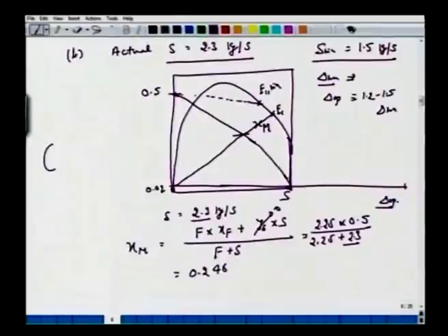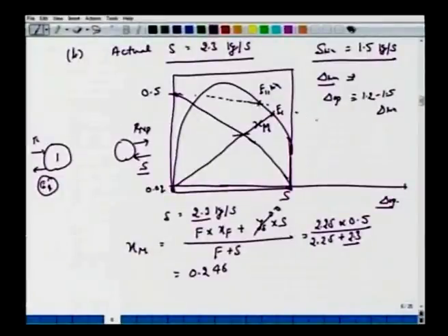So it is a multi-stage: feed getting in here, raffinate getting out here, the solvent getting in here, and we have E1 leaving from this stage 1. So when we take the larger amount of S, the concentration of solute in this extract phase is smaller. So this had corresponded to our del min. And now we chose operating S larger than this 2.3 kg. So when you extend this line here now, you will see that this will intersect much ahead of.